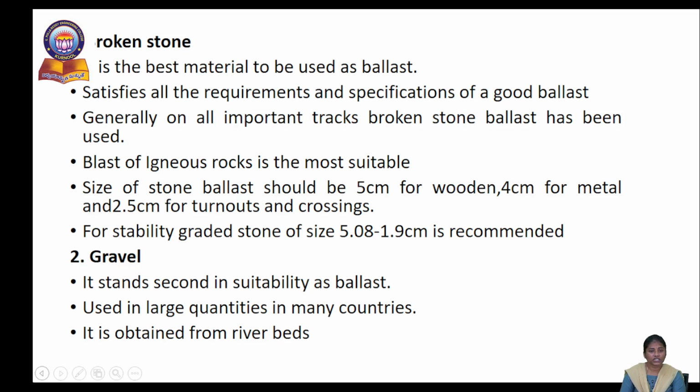Stone from igneous rocks is the most suitable, and the size of the stone ballast should be 5 centimeters if you use wooden sleepers, 4 centimeters for metal sleepers, and 2.5 centimeters for turnouts, points and crossings. For stability, graded stone of size 5.08 to 1.9 centimeters is recommended.